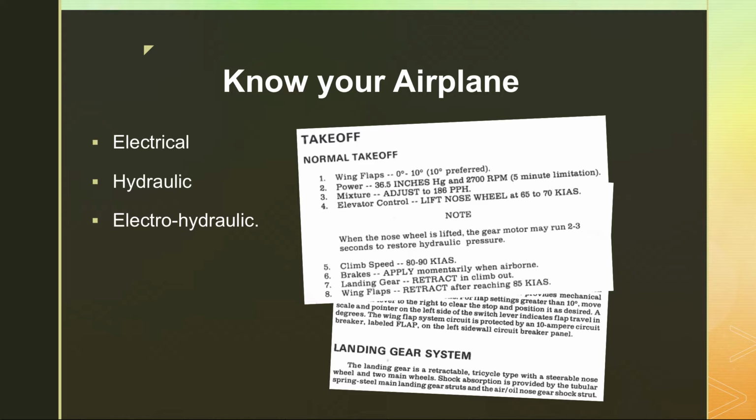Because yes, if you put the handle up on the ground, nothing's supposed to happen, but during the takeoff roll, the gear might start to retract prematurely. Another key thing to know about this aircraft is the way the Cessna main landing gear folds back into the fuselage. You need to make sure that you use the brakes to stop the wheels before you retract the landing gear into the fuselage. Otherwise, they might not go in at the right angle because of gyroscopic precession.